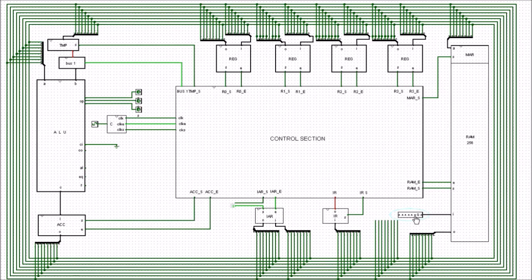So right now it's just going to be sitting all at 0. So let's say we put our instruction, and our initial instruction is all 1s. Okay, so in effect this instruction here is going to sit in the first memory location, then we're going to go to that memory location and take that information out and we're going to put it in the instruction register, and this here becomes the first instruction for a control section to act on.